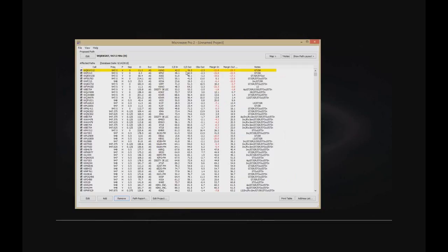In this case, it's a co-channel, so our C over I objective is going to be more than this probably. And you might want to ask the question, what C over I objective is it using? It used to be fairly simple, and if you uncheck that adjustment box, it's fairly simple: if it's a co-channel, in this case we're separated by 0 megahertz, it's going to use the 65 dB, and if it was first edition, it used 30. But since we're adjusting, that may not be the case.